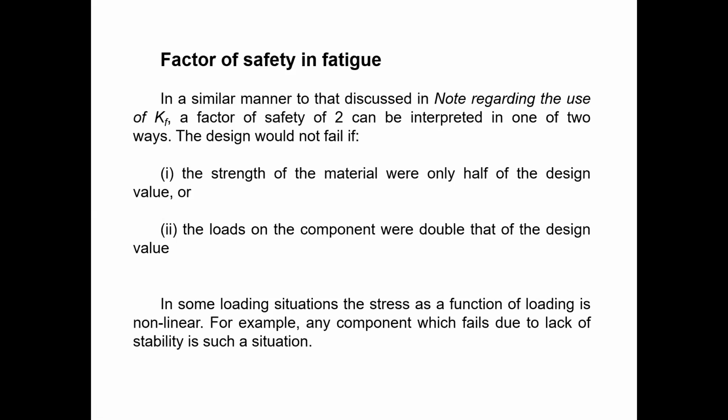Safety factor means the maximum stress you can apply on that specific element should be divided by the applied stress. So that is a factor of safety. So if it is equal to 2, like in here, that means the maximum stress you can apply on that particular element is 2 times what you are going to apply on the specimen. So that is a factor of safety. So you can design according to that if it is 2.